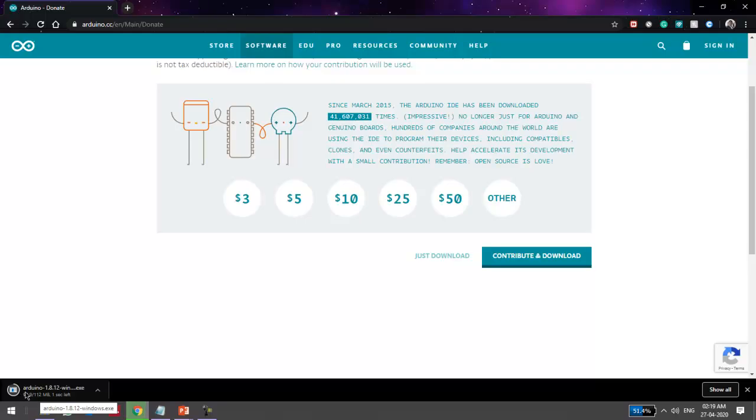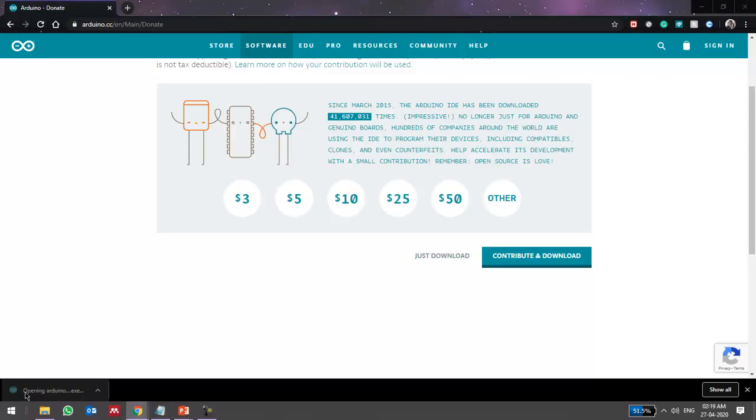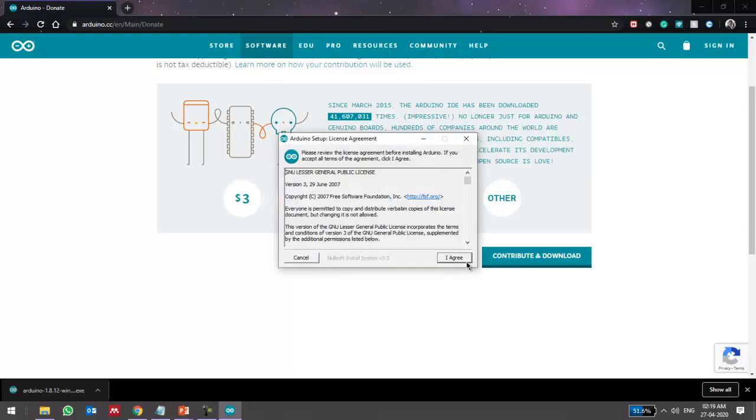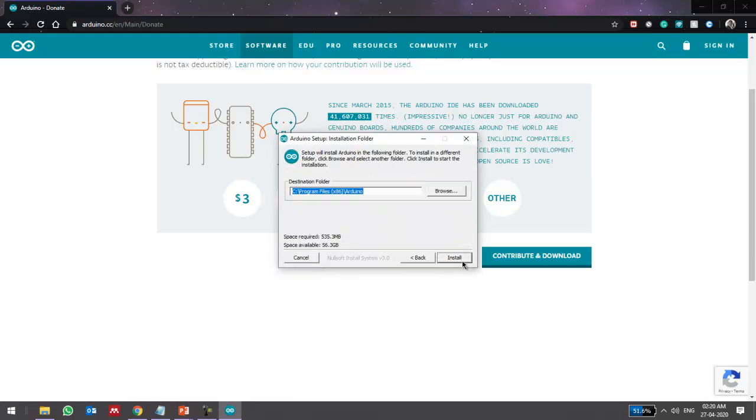Upon successful download, we are going to install this Arduino IDE onto our system by clicking on that .exe file. It asks for permission for installation. Give I agree, next, install. This process will enable you to install the Arduino IDE platform onto your system.